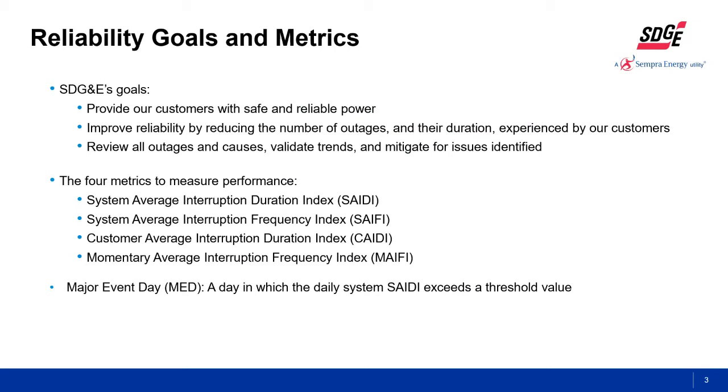Finally, there is a measure that's used, fortunately, very infrequently, and it's called a Major Event Day, or a MED. And that is a day in which the daily system SAIDI, that's the duration index, exceeds a threshold value.